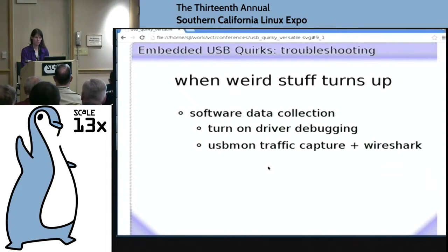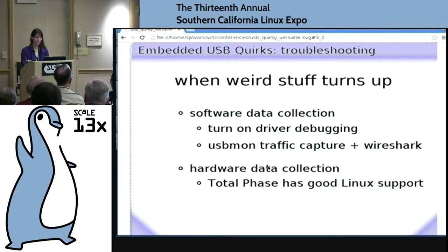Now, the USBmon traffic only goes so far because you are trusting what your drivers are telling you. Usually the USB core stuff, the low level stuff, will give you an accurate representation of what's going on, but it's not as complete as you can get with hardware.